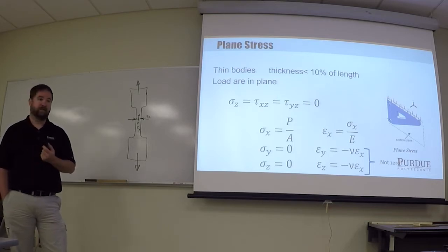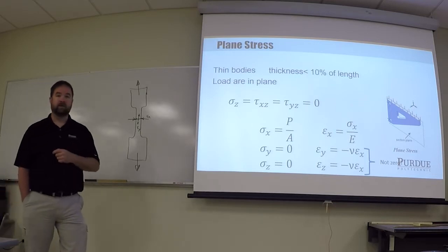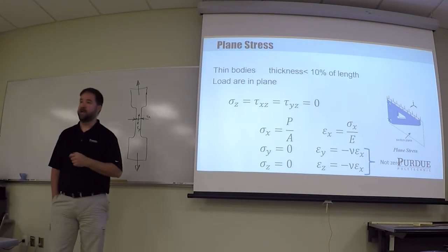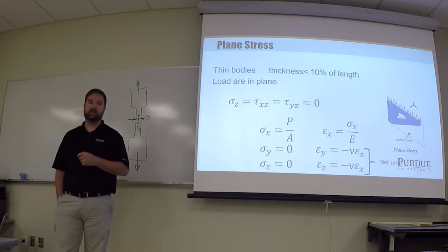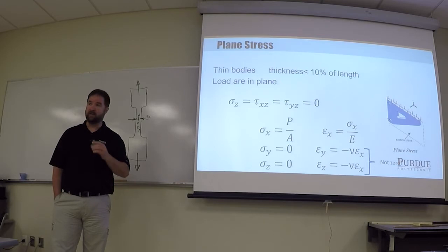A propane tank would be the same thing. We can expand this to a lot of other things. When I was working in industry, almost everything we built was made out of 1/4 inch or 3/8 inch thick steel plates. And so we did almost all of our analysis assuming plane stress, and we just modeled all of those plates as two-dimensional elements.